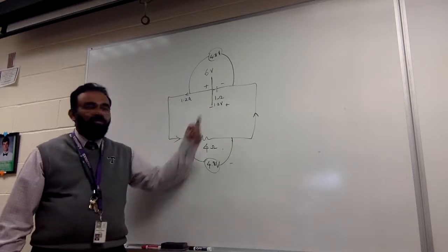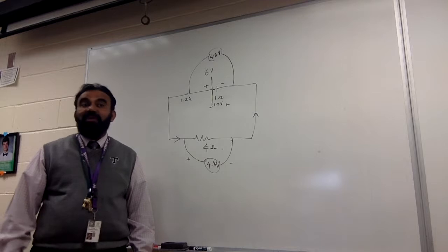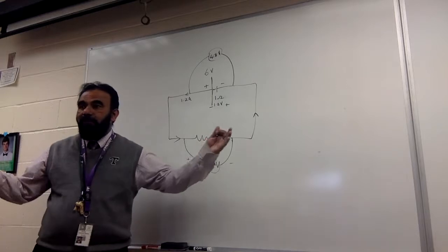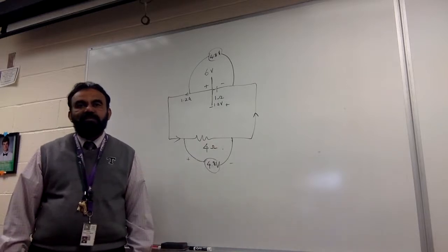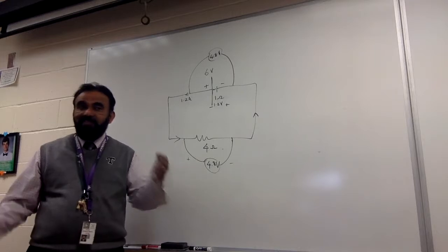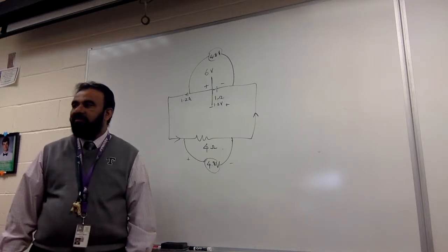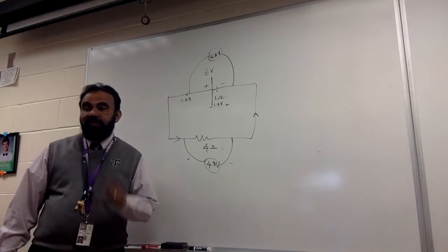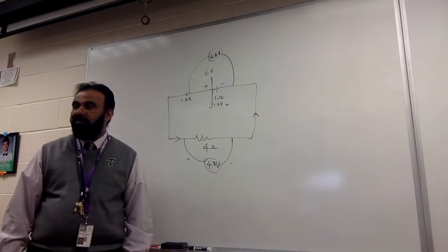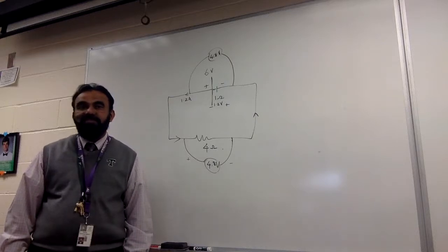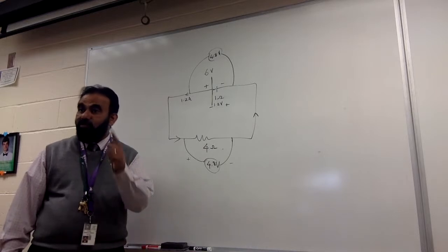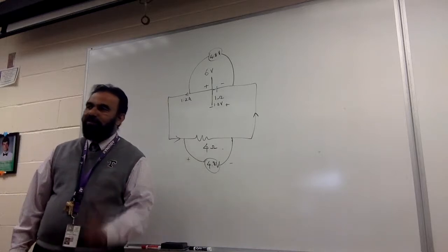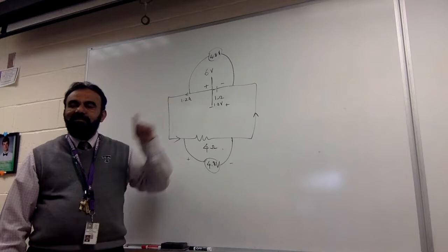So what is ideal then? If you know that this is useless, you like to have an internal resistance of 0. But the problem is, if you want internal resistance of 0, you need to have a huge power supply. So that's why I said a car battery has a resistance of like 0.1 ohms. But when you're talking about a current of 30-40 amperes, even the 0.1 ohms will make a big difference. You know what I'm saying? It will create a big drop.